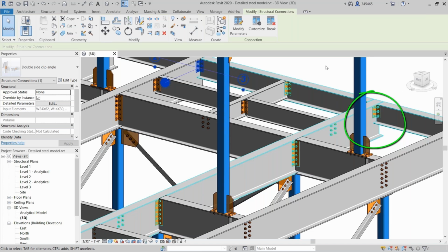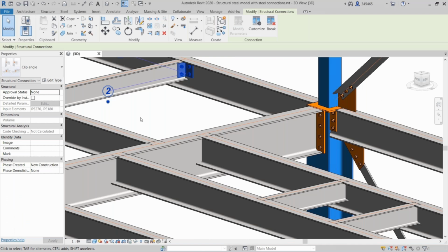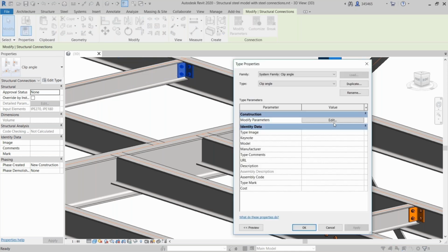Now we also have something called steel connection grouping. When you are working on steel, you will have a steel connection done on one of these plates. You can group them together into one single group. So if you have, say, 2 or 3 similar connections, you can group them together. You can make one the primary, so if you change one of its properties, it will automatically update and reflect on the rest of the group as well.